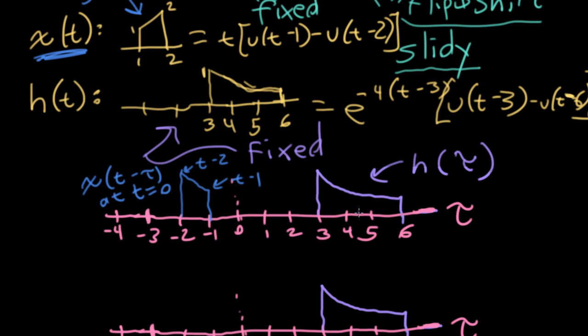When I analyze the convolution, I'll have 5 different cases here. The case shown on this graph represents no overlap on the left. So we have the function that's sliding to the left of the purple block, and there's a large range, like where I've drawn in dotted here, that you could set t to move this block to. And what happens in this case is that all of the places where the function is purple, when you pointwise multiply it with the blue function, well, the blue function is 0 in that region. And all of the places where you have the blue function, well, the purple function is 0 in that region. So when you do that pointwise multiply, the entire function is 0.